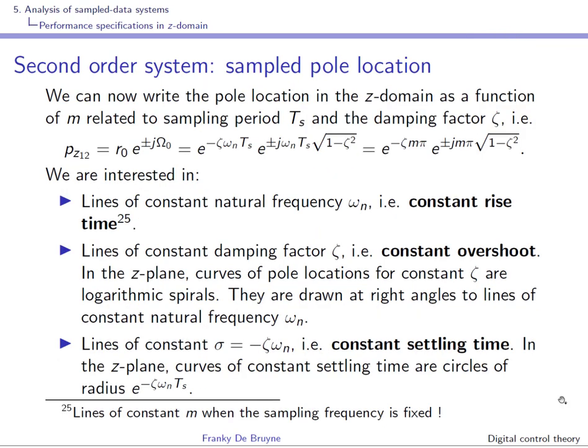Well, we have seen previously, and also in the course of state space control methods, that you can choose this method of dominant second order poles, and if you put those poles in the performance region, you can impose a given specification in terms of the rise time, the overshoot, and the settling time. We'll do something similar here in the Z domain.